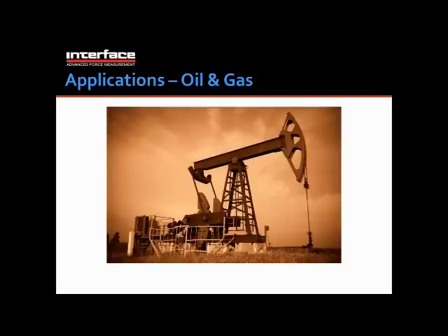Also, downhole applications exist where you may need to monitor the axial, the torsional, or even the bending moment load that can develop in downhole tool strings, very, very deep down under the Earth's surface. There are some other challenges on those applications. Another popular application would be hook load monitoring. That's basically another line tension type measurement. Those are a little less intrusive though in the structural system.